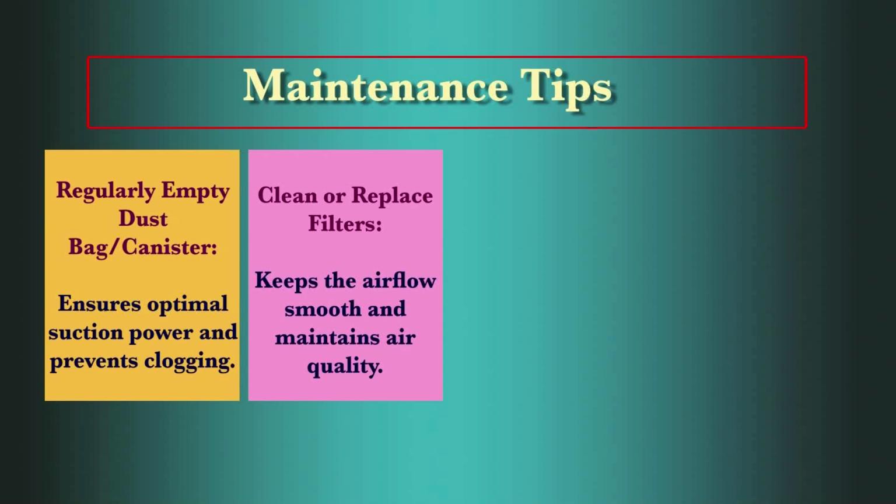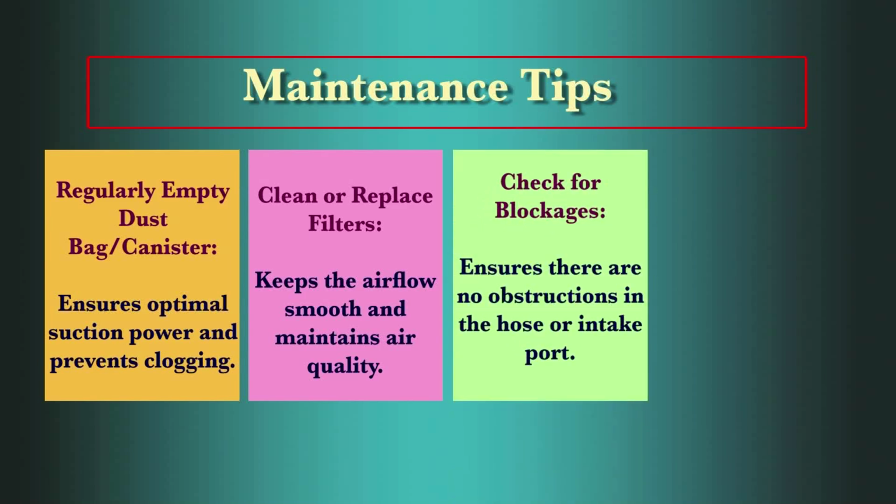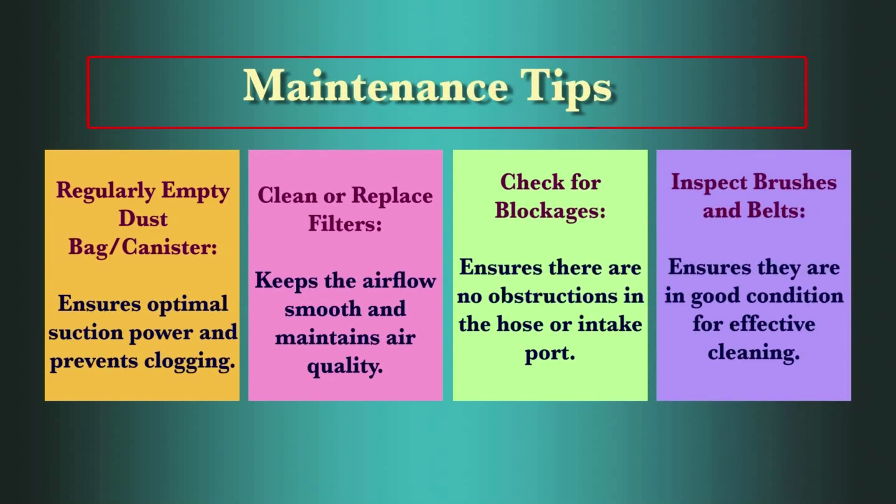Number two, clean or maybe replace the filters. Keeps the airflow smooth and maintains air quality. Number three, check for blockage. Ensure there are no obstructions in the hose or the intake port. Then number four, inspect the brushes and the belts. Ensure they are in good condition for effective cleaning.